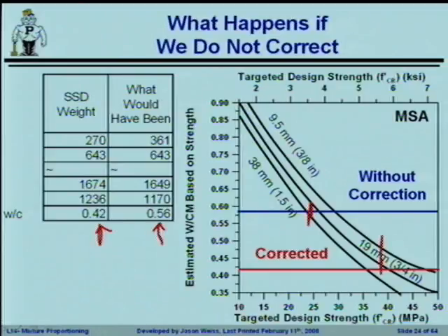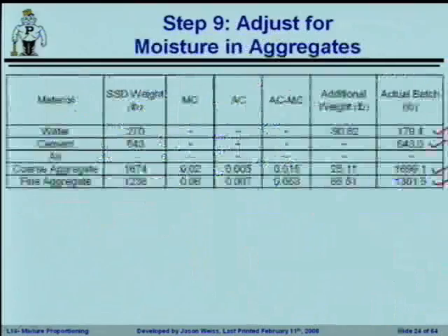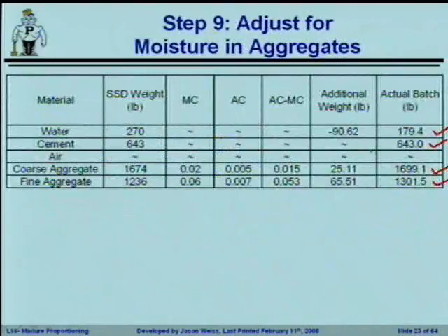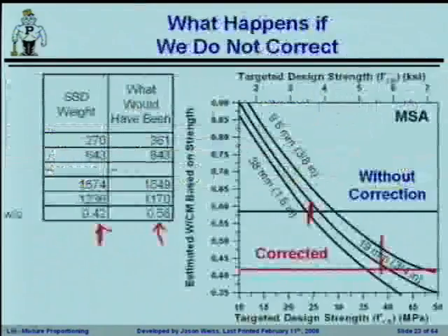That's one of the things that's most commonly done, because you'll notice in these calcs we didn't say anything about the air, because obviously air is going to be really, really light. So we're going to assume that it's effectively 0. But if we start not getting 6% air and we get 3% air, this won't actually yield a cubic yard of concrete. It's going to yield a smaller amount. So if you fill up a bucket, it's going to weigh more for that concrete. Okay?